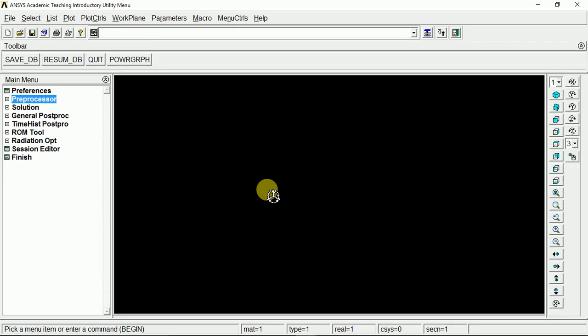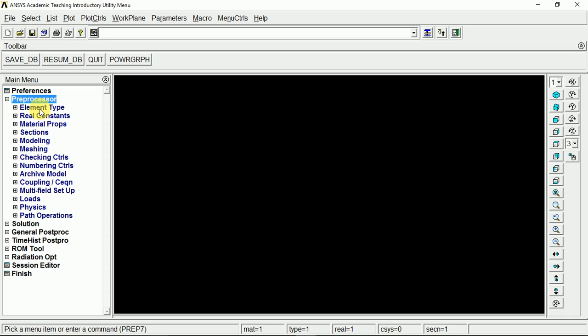Alright, in this video for BYU's MB372 class, I'm going to be talking about how to add an element type and a material property to our model. As a quick review, an element is basically the way ANSYS represents your geometry in your model. If I could draw a straight line, ANSYS wouldn't know whether to turn that into a wire, an electrical diagram, or a beam, or a truss element, or a thermal boundary. It wouldn't know what to do with that line until I define an element type.